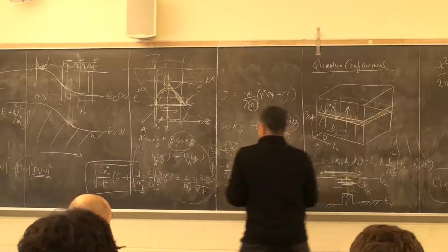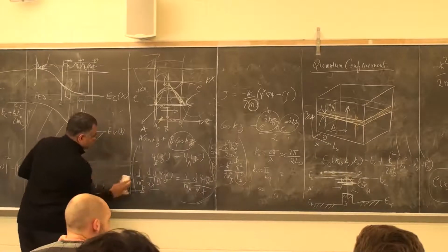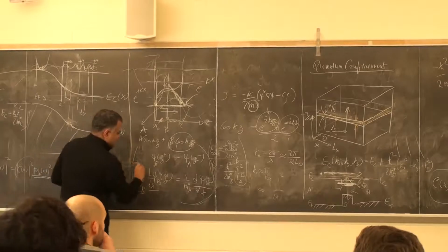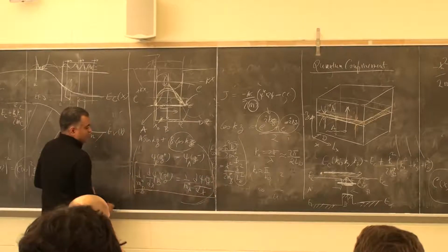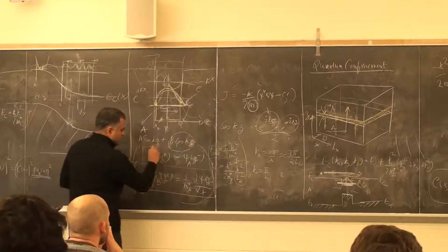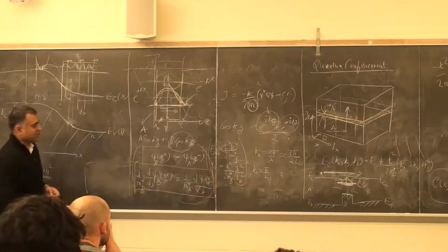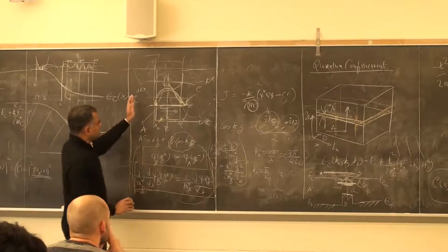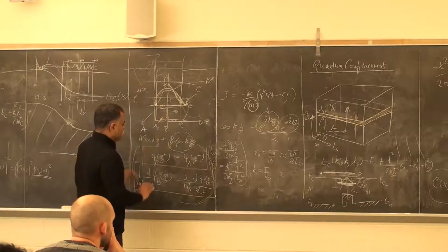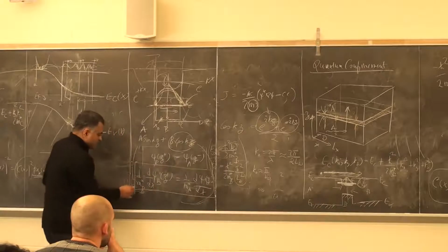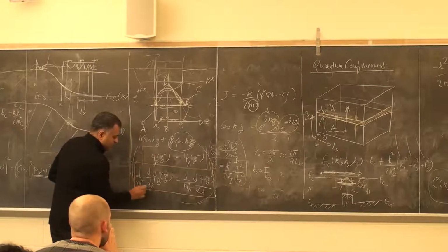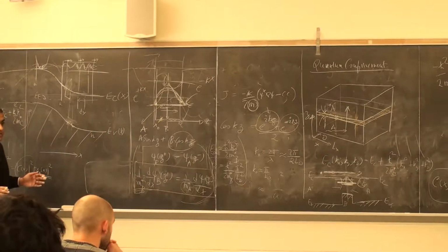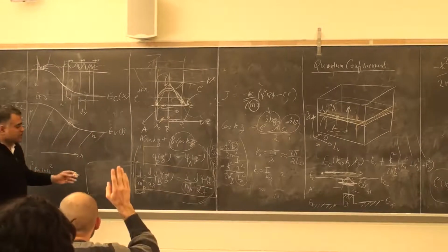So the effective mass, so this is a continuity equation. This is the matching condition for the derivative of wave functions, and this is the matching condition for just the wave function across any heterojunction. So compound semiconductors, material A, material B, or any heterojunction. What I was trying to get to is, in traditional quantum mechanics books, you will not see this term, because they're not talking about semiconductors or different effective masses across the junction. So this is something that comes about.